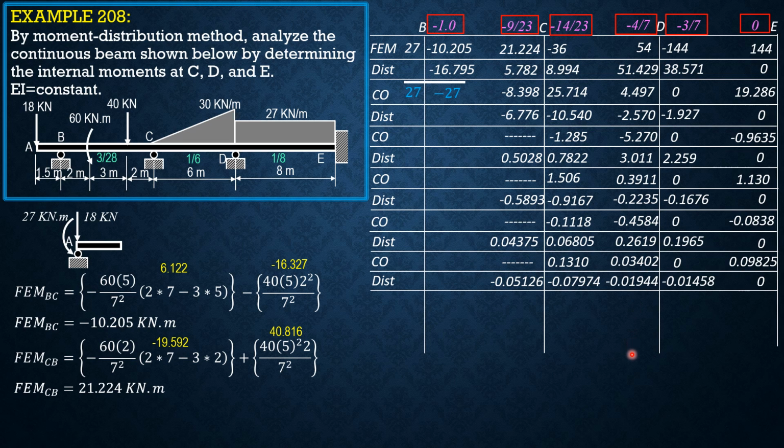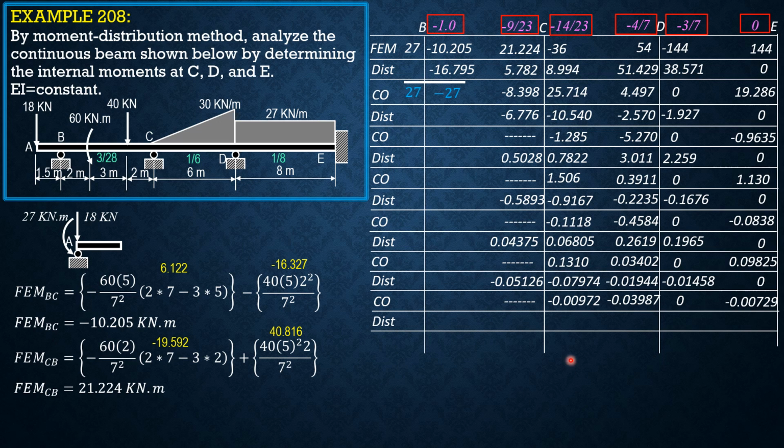Adding the values in this column, we have 105.066. So in this column, negative 105.066. In this column, the value is 163.46. Therefore, the moment at B is negative 11.742. It was negative 11.738. So there's a very small discrepancy because this is by approximate method. So if you continue up to here, maybe one round, then they might be the same in three-moment equation results. But this value is similar to three-moment equation. This one is a little bit close.